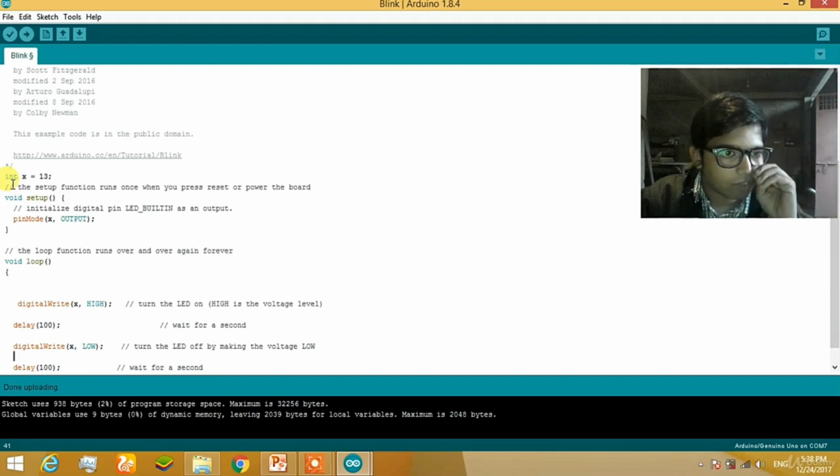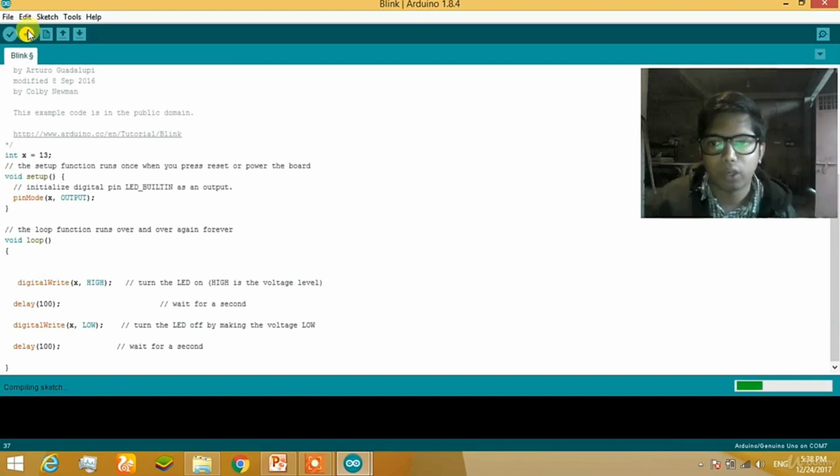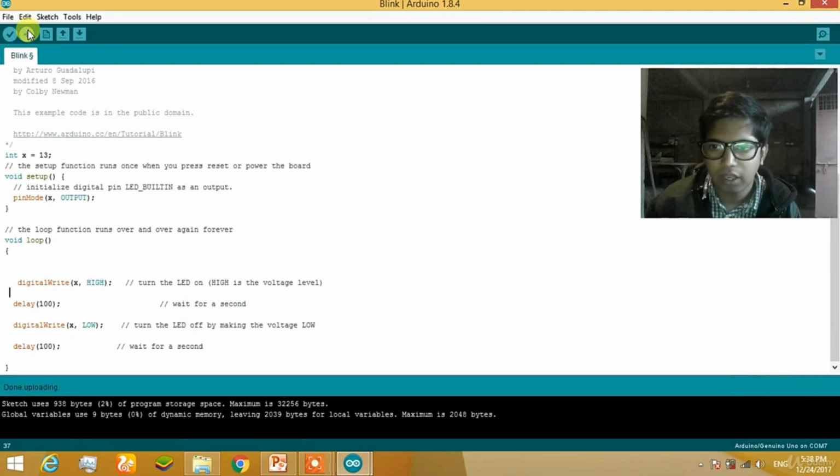Now let's get down to the void loop. You can see that in void loop, digitalWrite x is HIGH for 100 milliseconds, x is LOW for the next 100 milliseconds, and it is written in the loop, so it will run for infinitely long. Let's check it. The upload of the program is done, and you can see that it is running infinitely long. Let's get to another section.